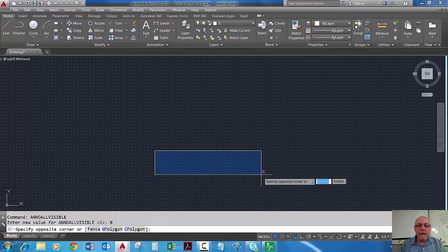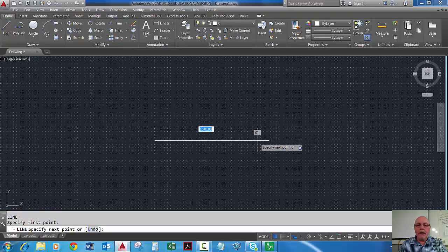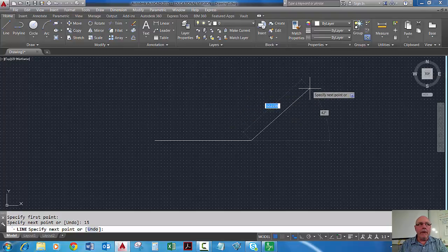So I'm going to pick a line start point, and we'll go out here and we can see the first little highlighted box is asking for a length. So you could accept that length that you're showing, or you can enter a length. Okay, so we'll just put on there, that looks pretty large, but we'll put 15 and enter. Okay, and then we want to go up at a particular angle and distance. So we're looking at 10.